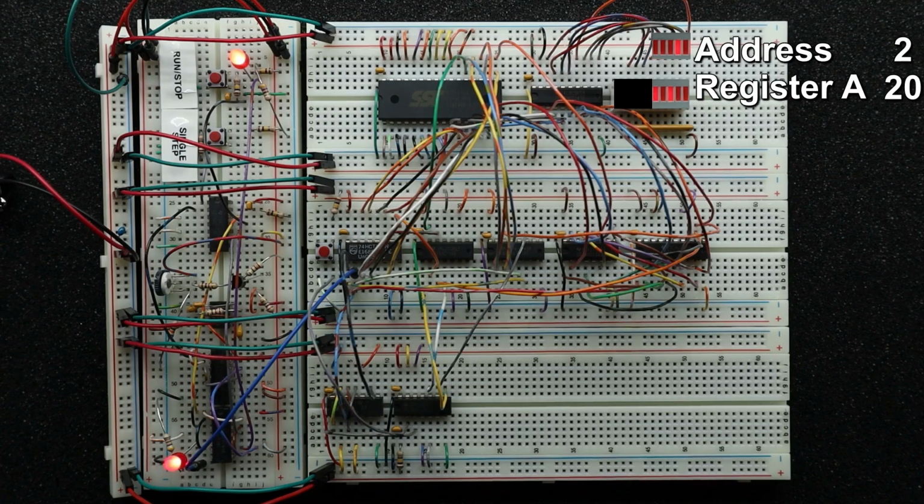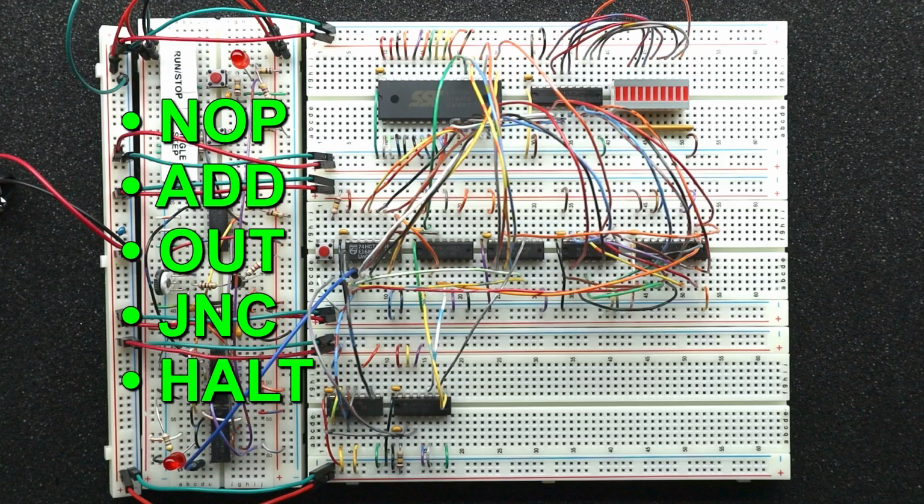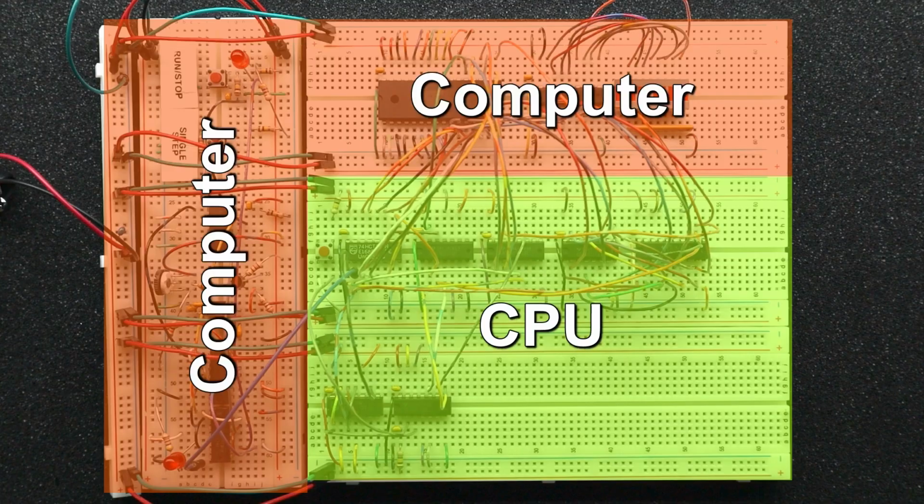Ha ha ha! So now I'm about halfway through designing the Plague Mark II. And I mentioned in the first video that it would take about 7 logic ICs to get to this point. Let's count them. 1, 2, 3, 4, 5, 6, and 7. Spot on thus far. So, what do we have at this point? We have a simple CPU that can execute 5 assembly language instructions: no-op, add, out, jump if not carry, and halt. The CPU is contained on these 2 breadboards, and the remainder of the circuit is part of the computer that contains the CPU. Not very impressive, but it does correctly execute the code that we write for it.